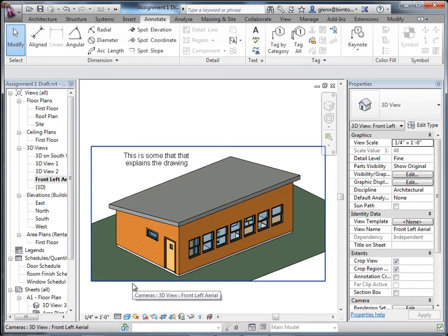The funny thing, and what's sort of weird about working on the computer, is it's relatively scaleless up here, because you just keep on zooming in and zooming out. You don't really have much of a sense of scale until it actually gets plotted out. So watch out for that a little bit. And then in terms of standard scales, for buildings like this, which are relatively small, quarter scale is a really common size. I do that for most residential construction. When you start getting commercial construction or bigger buildings, then 1/8 scale or 1/16 scale is much more common. It's good to see how much information you can fit on a sheet. You like it to be as big as possible without being overly big. And those are some scales that people will understand pretty well.